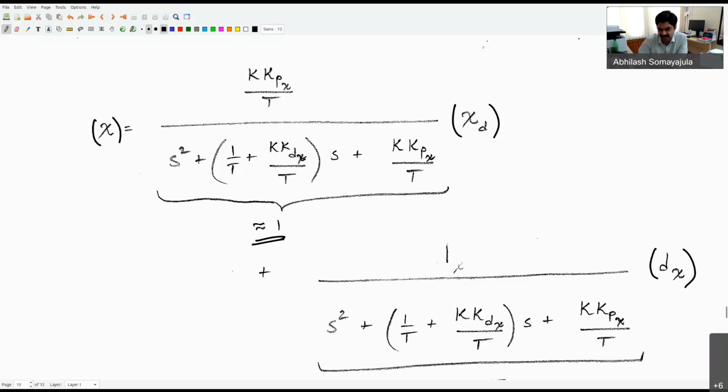Now, the idea is, why did I not introduce an integral law? We already talked about that. We could have introduced an integral law here in order to take care of it. But the problem is I want to do the integral at the outer loop scenario so that I don't have two cascading inner loops. Two cascading integrators may pose more challenging problems later on. So that is why I'm trying to put my integrator on the outer loop as compared to the inner loop. So on the inner loop, I'm happy with the fact that yes, there can be some steady state disturbances, but I'll close the loop in the outer side.